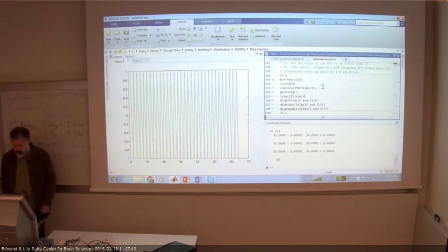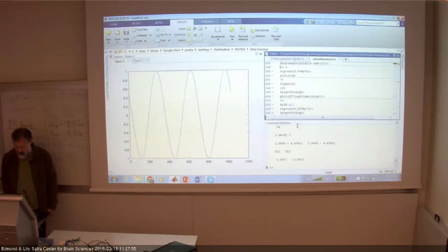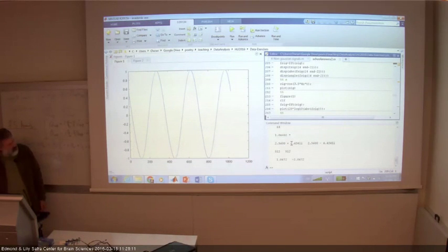Next I wanted you to see what happens with a phase. Again, this reproduces a thing that we did in class. So I get a 3 Hertz sample at 1024 with a phase of pi over 3. And I display, first of all, the corresponding entries. So entry 4 and n minus 2. These are the two numbers. You see that they are complex conjugate.